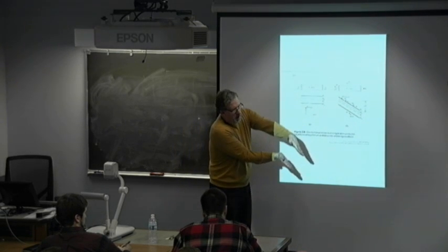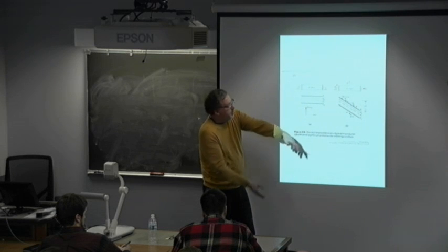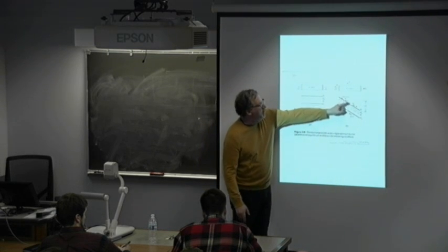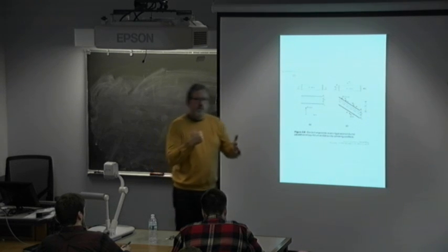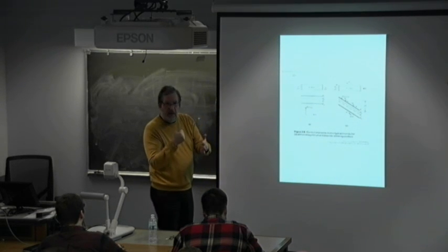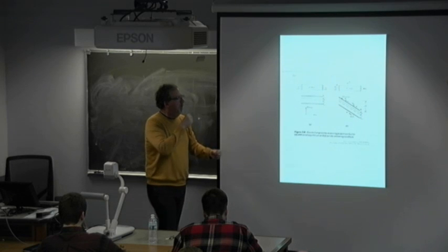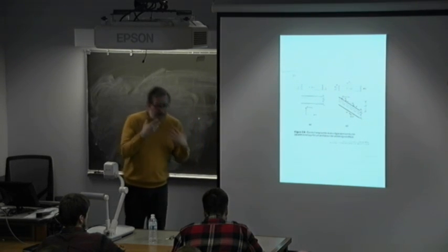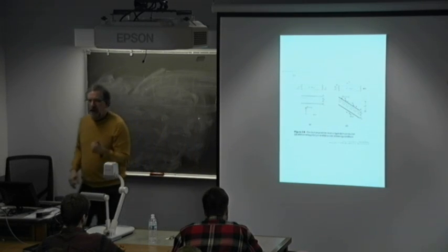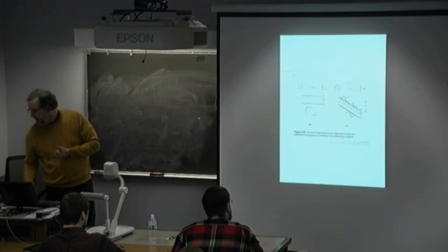If it distorts so much that this kinetic energy, when it hits the lattice and scatters, if it's able to impart 1/2 mv squared kinetic energy equal to or greater than the band gap energy, then you have an opportunity for an avalanche multiplication event.